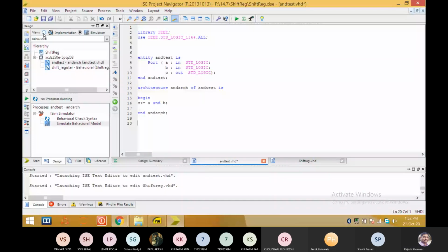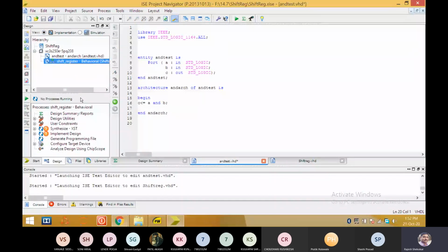After that, I want to go for the next stages of the design flow. As we have seen in the first unit, there are multiple steps for getting the file downloaded into the FPGA or CPLD. For getting the bit file at the last stage of that design flow, we should go for the synthesis. So before synthesis, we'll go for one thing that is called check syntax.